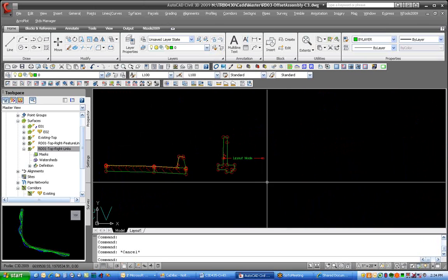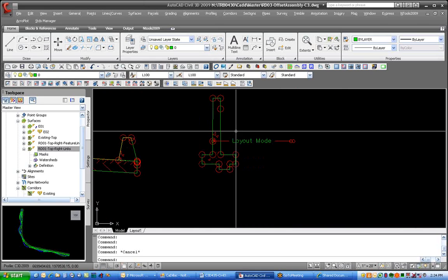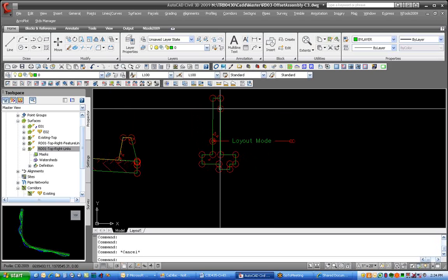the retaining walls here. A couple of things we did: one, the Civil 3D one we found put the key on the low side instead of the high, deep side, so that's wrong. The other thing is this point here in the Civil 3D sub-assemblies, the only thing you connect this to is a surface. So what they had to do on Route 1 is they had the profile where they wanted the existing ground to be. Then they had to bring that in as a feature line, offset it, create feature lines, build a surface model of the profile, and then they could attach that surface to the sub-assembly through the corridor properties.